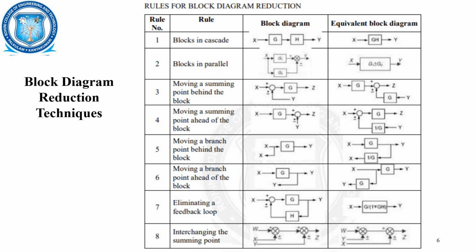So what we have to do is insert a block into this branch at the summing point. While inserting, we have to multiply with g, because normally the value here is x plus or minus y, let us consider this as plus, x plus y into g. So what is the answer here? It is xg plus yg. Hence the z value here should be the same.